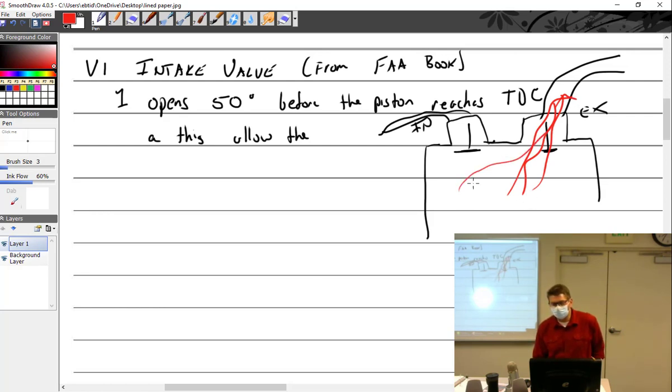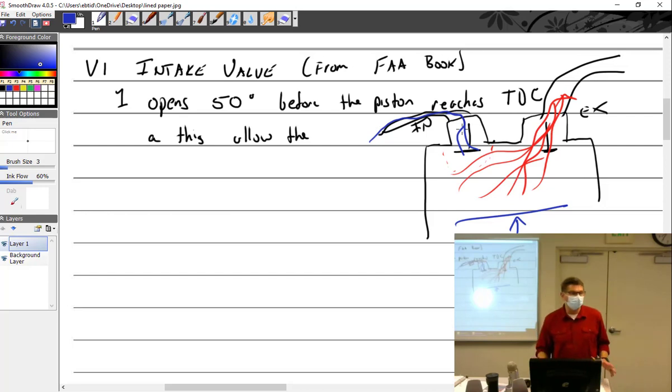But this creates, if you will, the draft across here, and kind of, I hate to use the word, but I will, sort of a Venturi effect, and this drawing out creates a low pressure in this area. And because that's a low pressure in this area, it helps to draw the fuel air mixture in. It starts coming in already, even though the piston is actually going up. Right, so there we go, and that's our whole thing. We can start the fresh fuel air mixture kind of rolling in at us right there, and that's what we want.